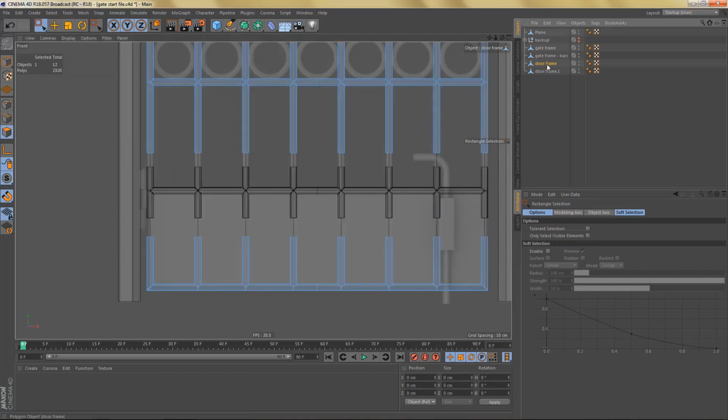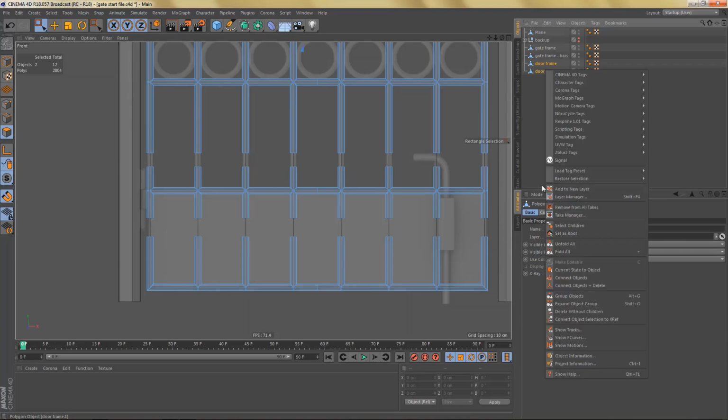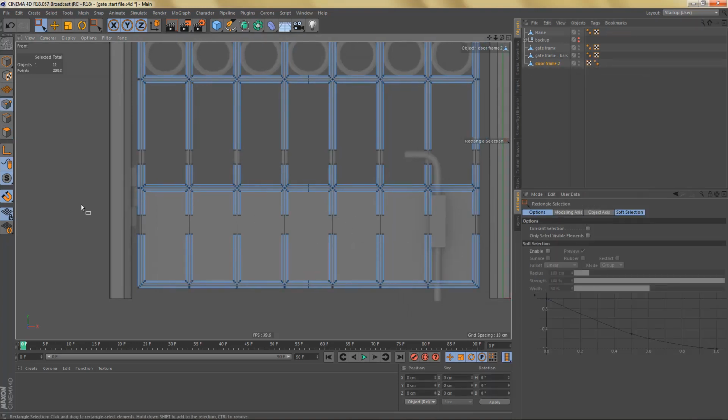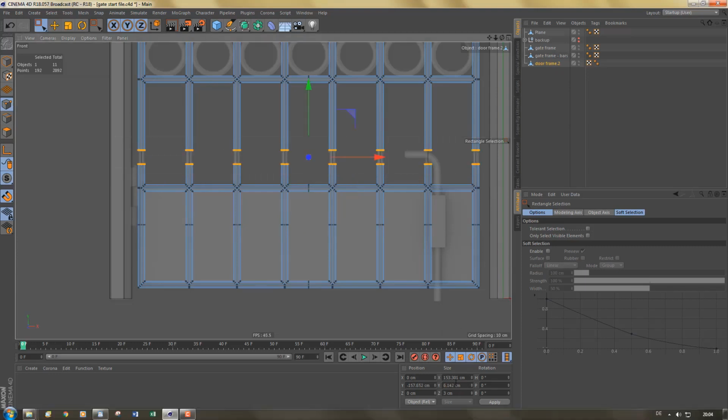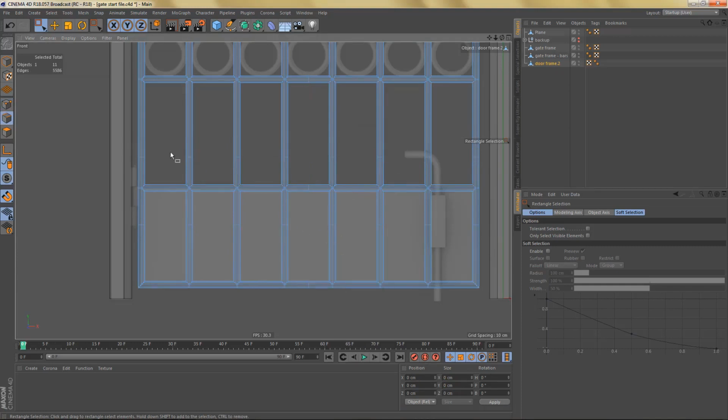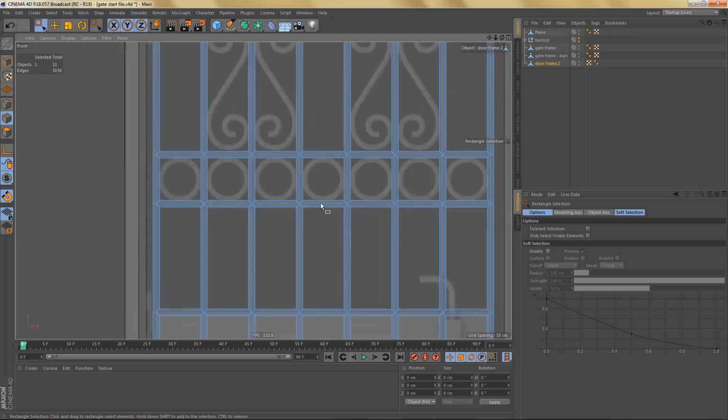And then we can select both of these objects, use connect objects and delete, and change the size of these points to 0. Same up here. Let's deselect everything, optimize the object, and in edge mode I'm going to dissolve these edges here. And we can also get rid of the ones at the center.